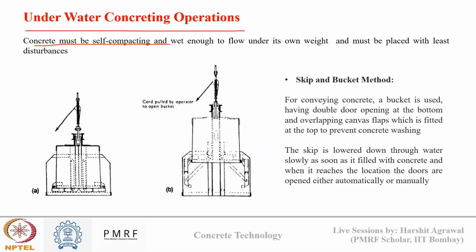My concrete should be self-compacting and wet enough to flow under its own weight, and it must be placed with least disturbance. There are different ways in which underwater concreting can be achieved. Since we are not applying any compaction, we need to find a way so that I can place my concrete efficiently, for which there are different ways. So first is the skip and bucket method.